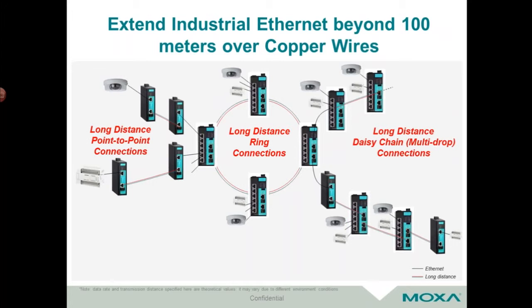The nice thing about DSL extenders as well is that they're extremely flexible in terms of what you can do to your topology and how far out from your main control center, or your main control room, you can basically extend them. There's two main types of Ethernet extenders on the market. One is a standalone Ethernet extender, and one is one that has Ethernet ports built into it. The standalone DSL extenders typically take in Ethernet on one side and put out across DSL on the other side. And so they're useful for a onesie-twosie run off of a main control area.